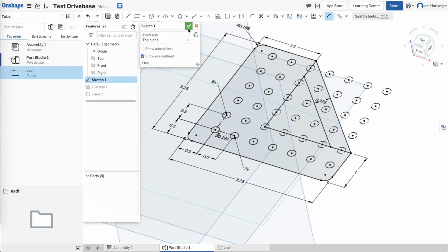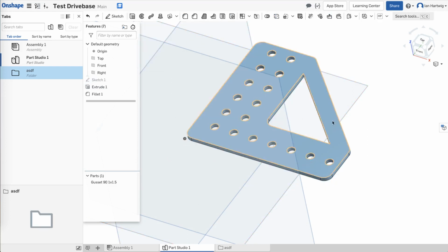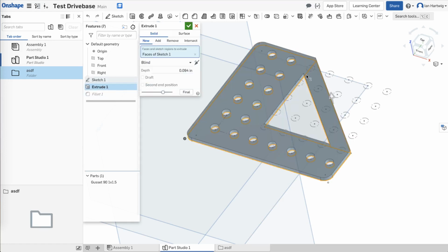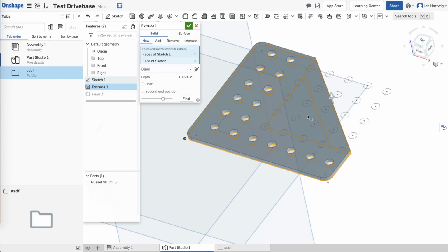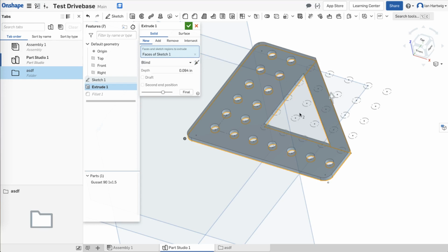So we're going to click OK on the sketch. And in this case, the extrude has actually selected that automatically to be part of the face. It is possible to edit it if, let's say, you actually wanted to include this middle section, you could click here and include it. But since we didn't actually want that, I'm going to go over to this box, and the new line that was added, we're going to click X right here to deselect it again. You could also click on it and then click on the space you wanted to remove. That would get rid of it.